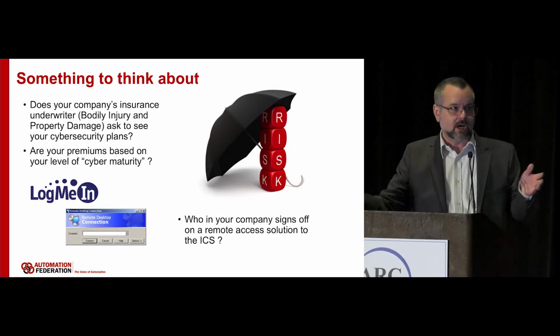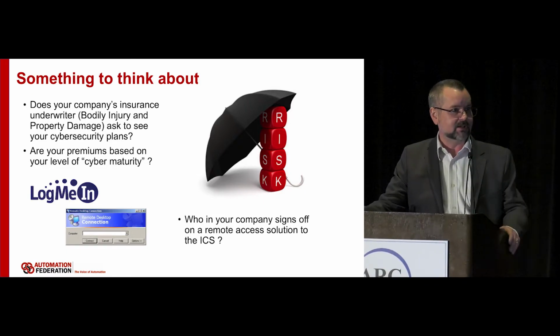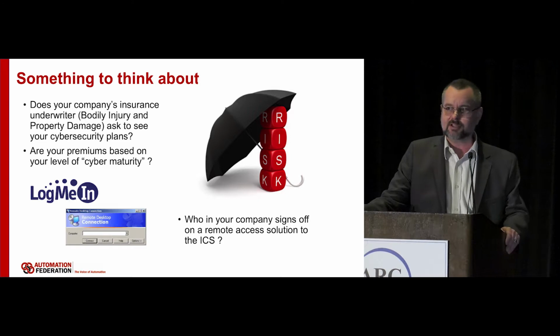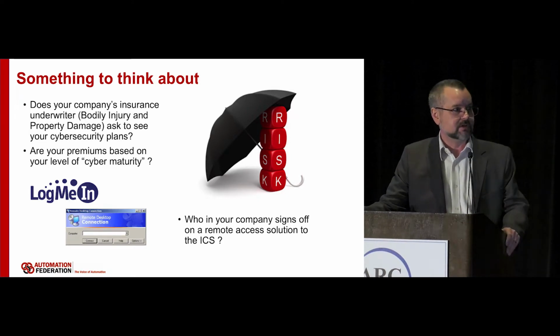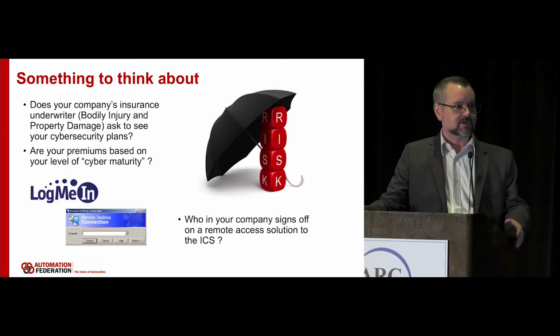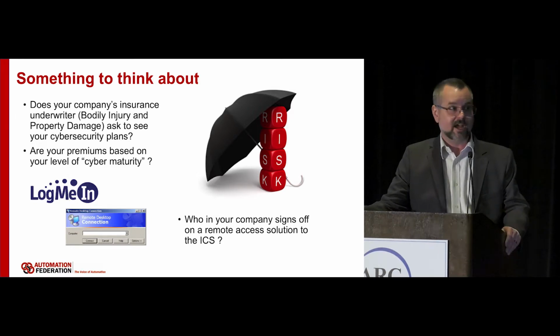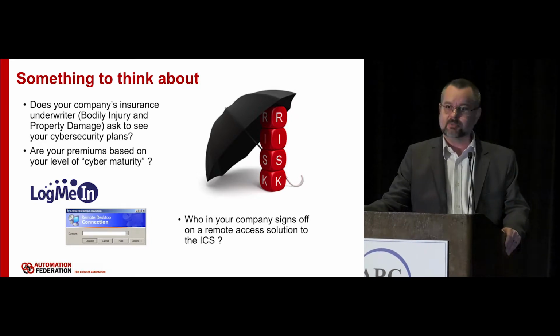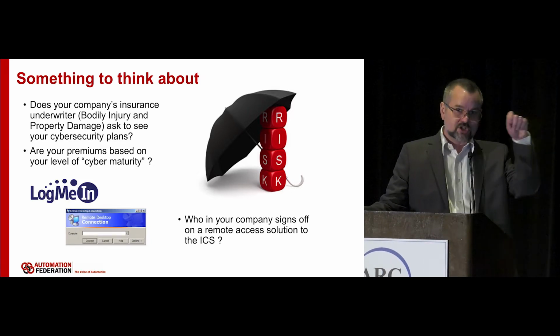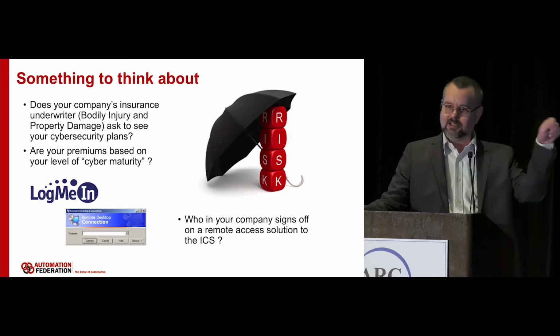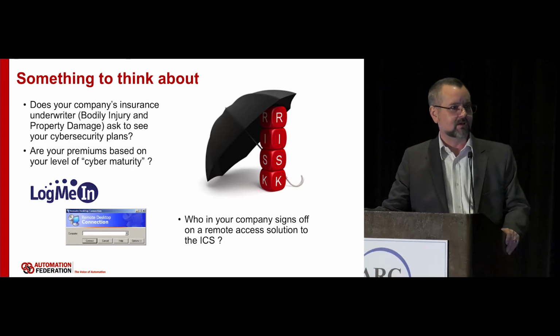I mean, most companies that actually manufacture something have some sort of risk in their process. I came out of pulp and paper, so boilers, recovery boilers, we had extensive insurance policies there, and I remember as a control system guy, you had to sit down with the Factory Mutual guy and walk through and show them that every interlock worked, and that yes, you would in fact protect the environment, right?